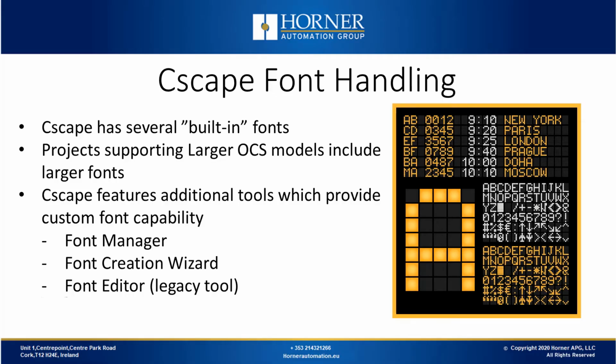Now let's talk about Cscape font handling. Cscape has several built-in fonts. Depending on the controller you're using, the fonts may vary. Cscape also has some tools for customizing fonts. Their tools include the Font Manager, the Font Creation Wizard, and the legacy tool called the Font Editor. The Font Editor won't be covered today, as it's a bit redundant. Everything you need to do with fonts can be done with the Font Manager and the Font Creation Wizard.